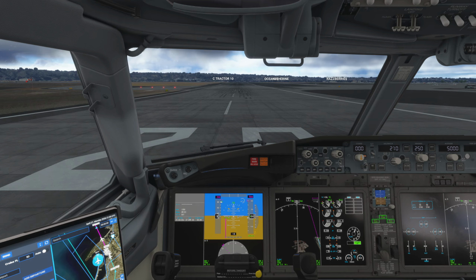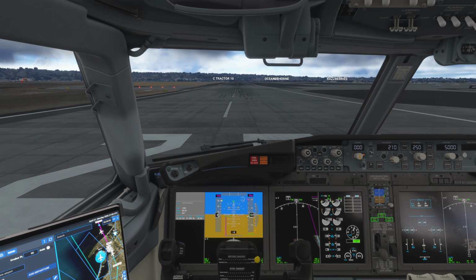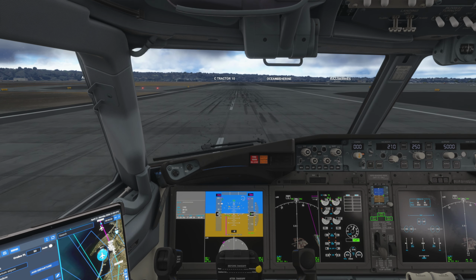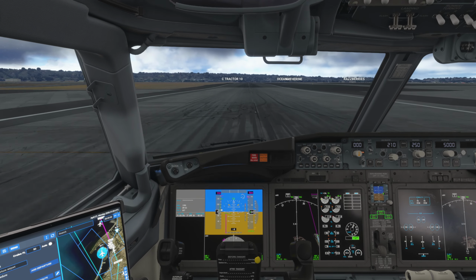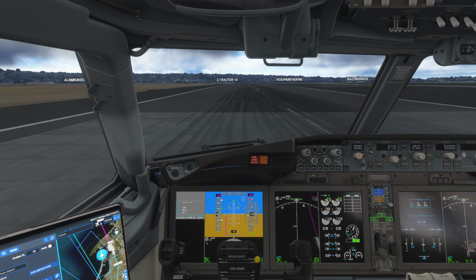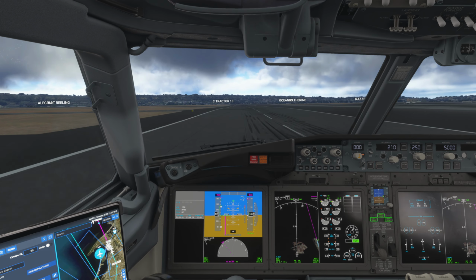Let's go ahead and get ready to take off here. Okay, let's release the emergency brake. Full throttle up. She's most likely going to give me some warnings with the flaps and the glide slope. For some reason, with this runway, I've been getting those warnings. Okay, at 100 knots, we're going to start rotating her. She's there. Let's go ahead and start rotating her up.